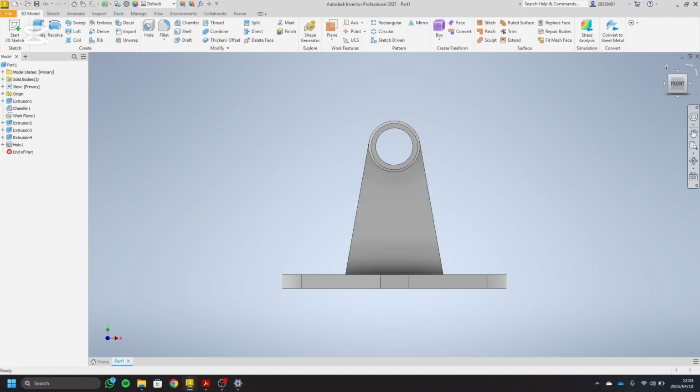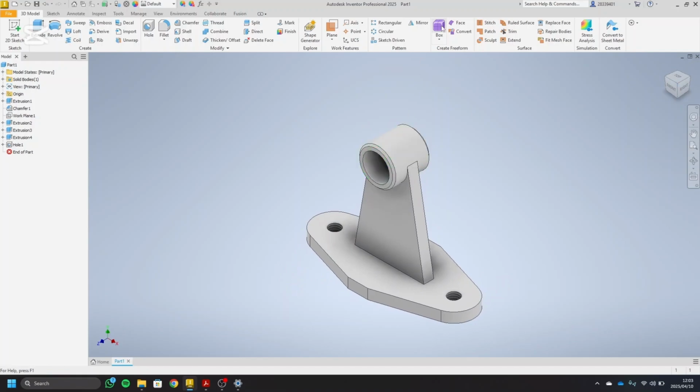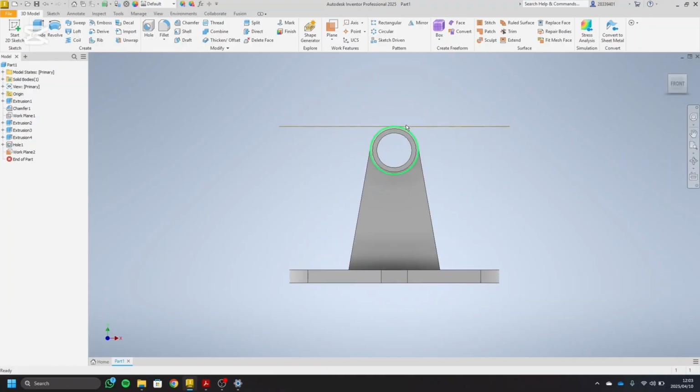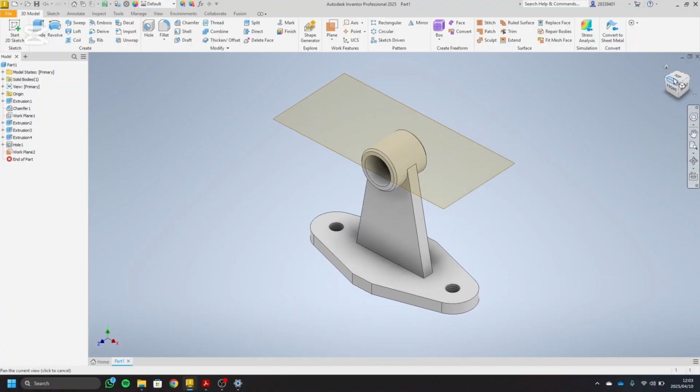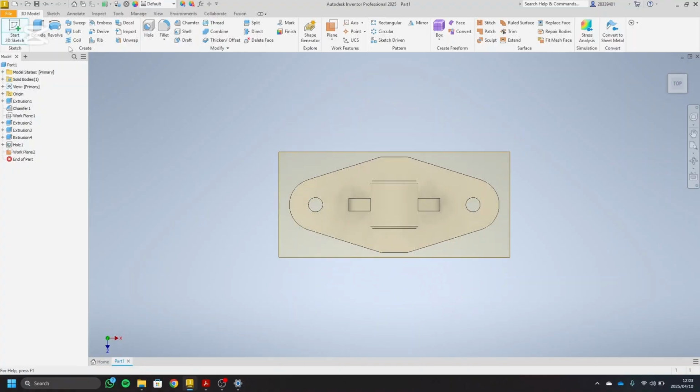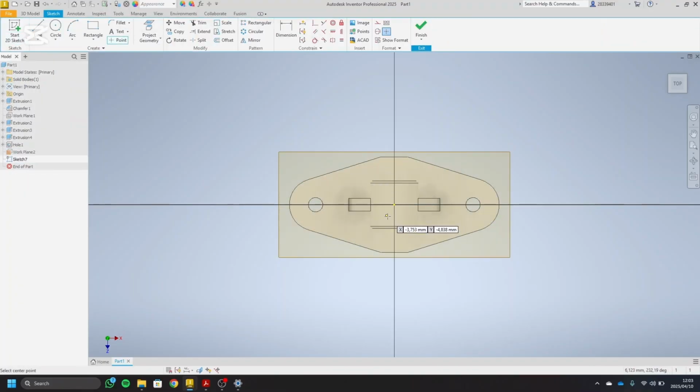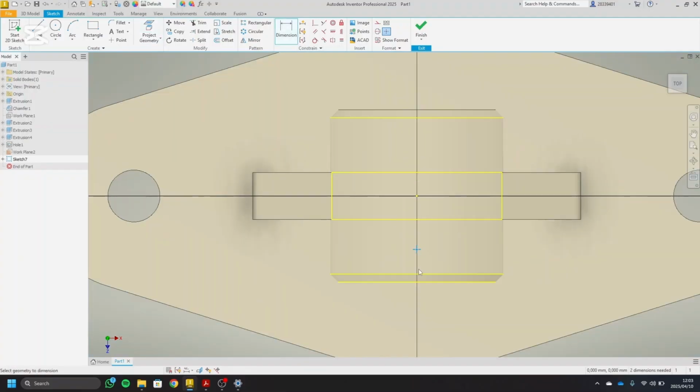So if we go here, we can create a plane on the surface, right? Just create something obviously like that. So there you can see, right? Let's create a new sketch on here, and let's take a point, place a point somewhere there. Just project geometry again. Okay, and we can dimension this point from this outer edge as 6 millimeters.